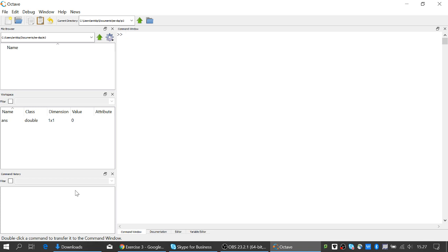So we have 0.5 times j, minus 0.5 times j, and here we have 0.5. So simple coordinates. These poles should be inside the unit circle because the radius is 1/2, right, 0.707, something like that.